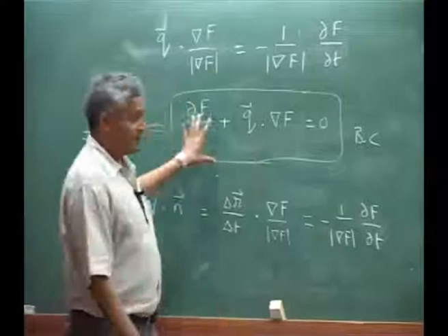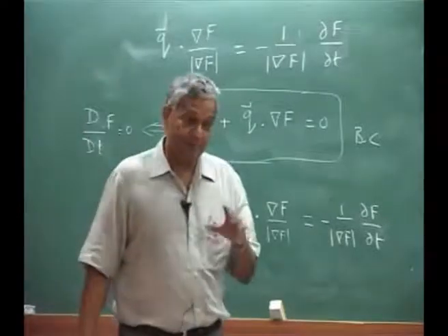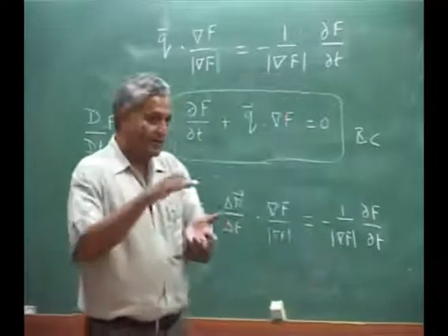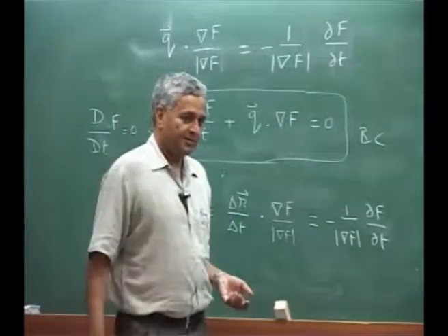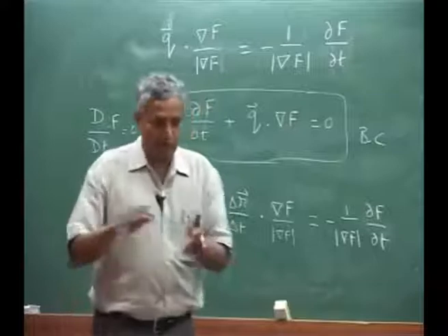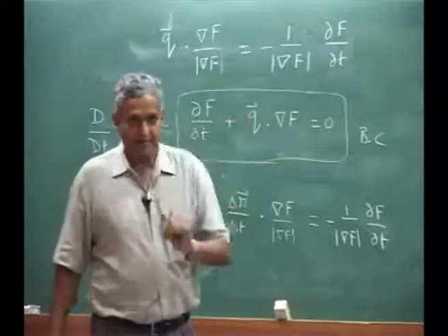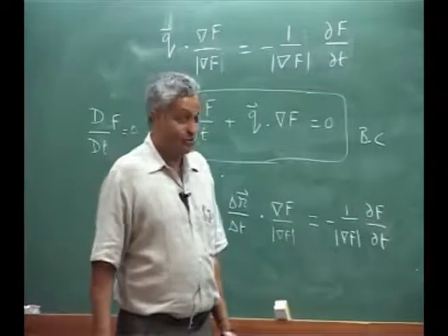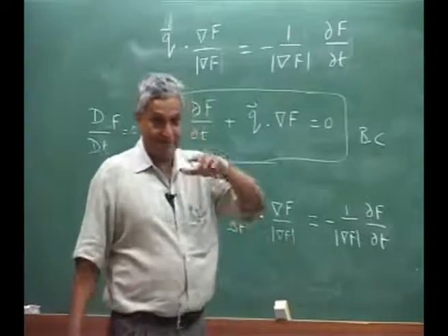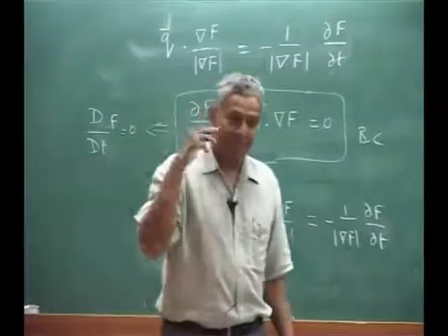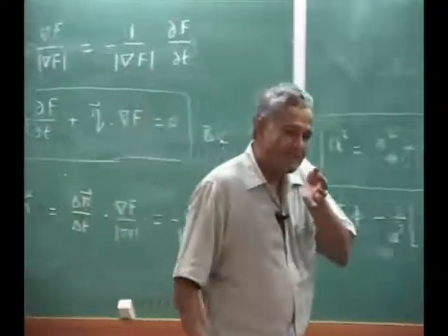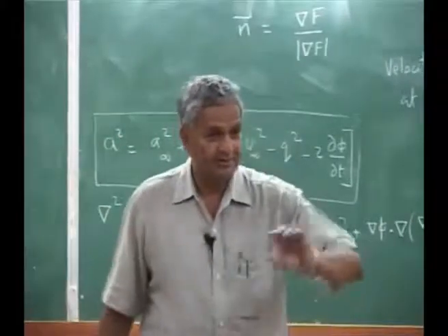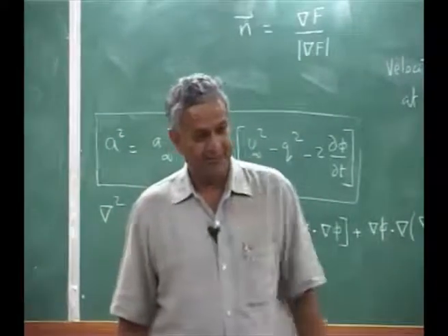So this equation, now we make approximate. This is where industrial codes come in. In an aerofoil, because our wing is an aerofoil, you have a top surface and a bottom surface. That means on the two surfaces you have to satisfy the boundary condition, top and bottom. Suppose it is a very thin aerofoil, you can project it onto a flat plate.